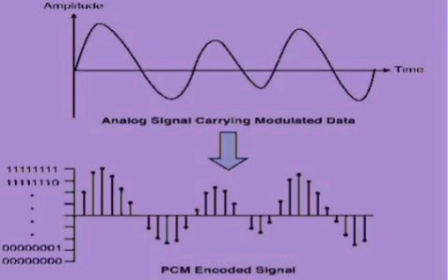Important pulse digital modulation techniques are pulse code modulation (PCM), delta modulation, and differential pulse code modulation. PCM. In this modulation scheme, we first sample the analog signal, then quantize it to convert into levels and encode it to then send it in the form of digital codes.